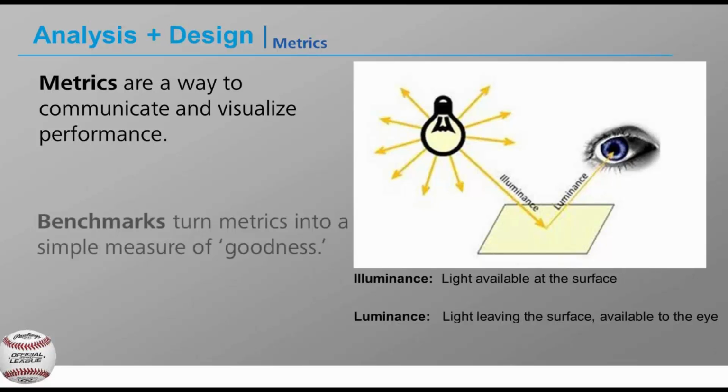So what we're looking at using is the illuminance value. Illuminance tells us how much light is available to be used on a surface. This is one of the most important metrics in daylighting performance. You can imagine that the reason we have light fixtures is to have light fall on the desk, so it can be useful for writing, reading, etc. If we can do that with daylighting, all the better. So these are some typical benchmarks for foot candle levels for different uses.